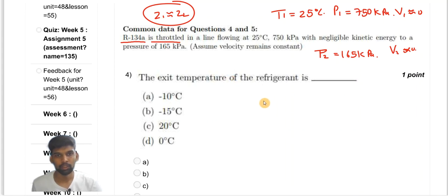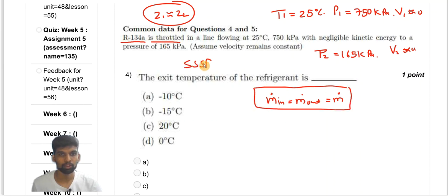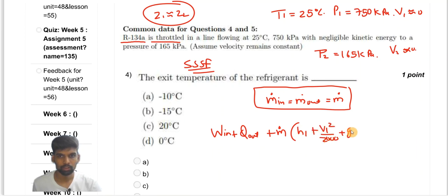Then the exit temperature of the refrigerant. The mass flow rate will obviously remain the same, m dot in is equal to m dot out. Assuming it as a steady state, steady flow process, and applying mass balance. Similarly, applying energy balance, what do we get? No work is done, but still let me write: h1 plus V1 square by 2000 plus g z1 by 1000, plus Q in, equals W out plus m dot h2 plus V2...